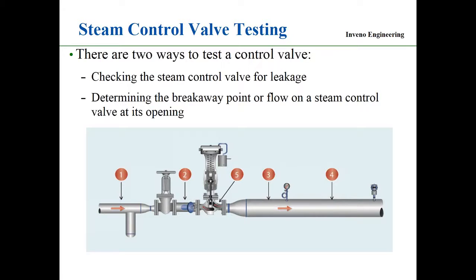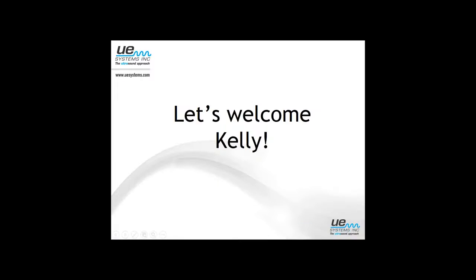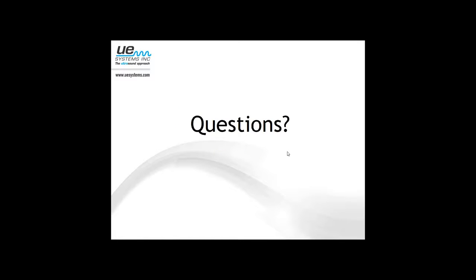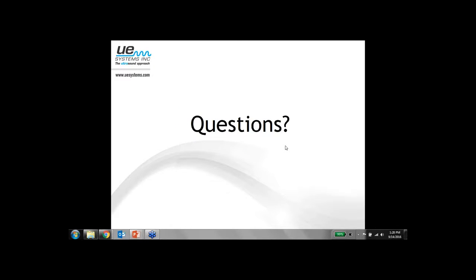And then this other person asks, if valves and steam traps are surrounded by insulation, how do you test them with ultrasound? Again, if insulation is a factor and it's permanent insulation, make a test port where the stethoscope module will go through and make contact with the pipe, and then once the test is done, plug that port. That gives you access from that day forward: you go up, look for the plug in the insulation, remove it, and then the probe can go in, which is done all the time.